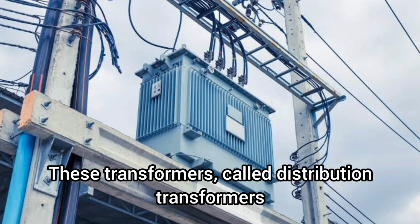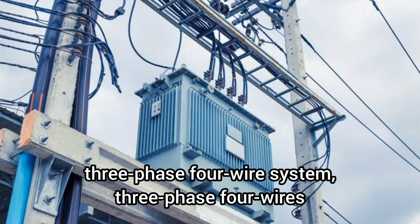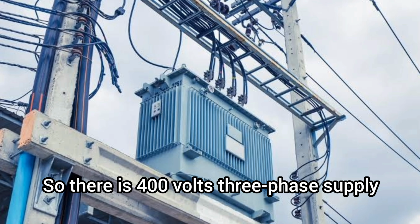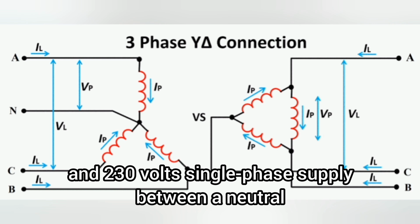These transformers, called distribution transformers, use a three-phase, four-wire system, also known as star connection. So there is a 400 volts, three-phase supply system, between any two phases and 230 volts, single-phase supply, between neutral and phase live wires.